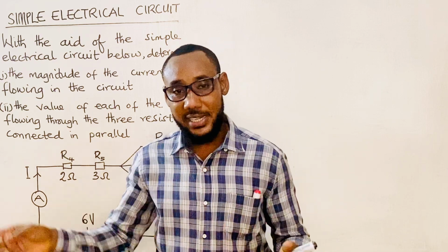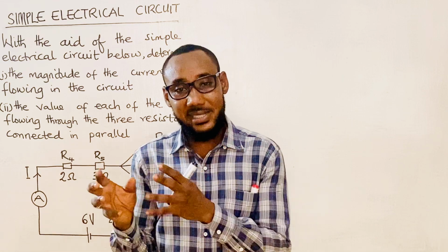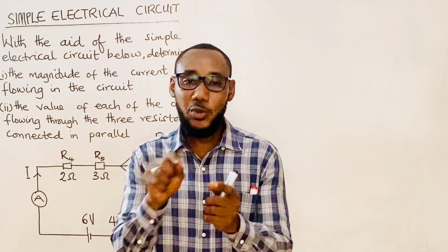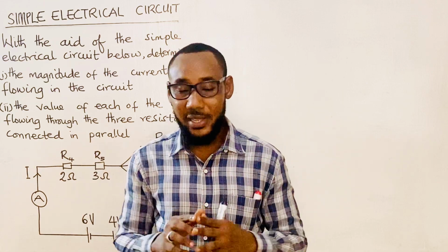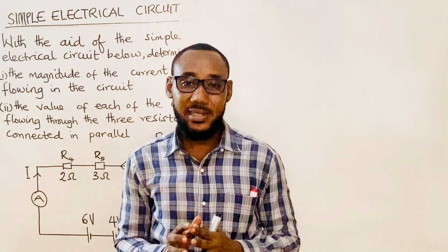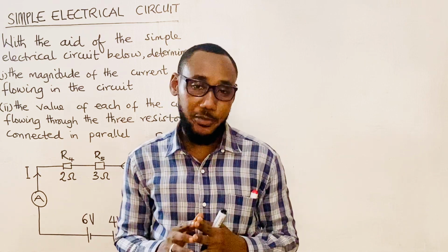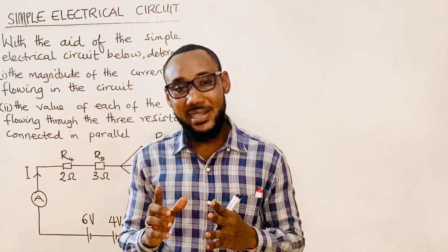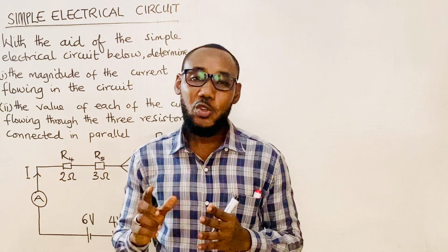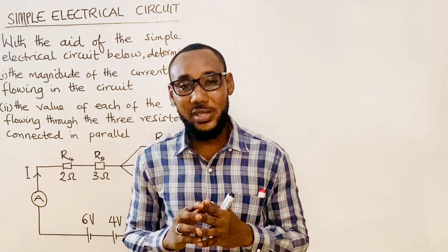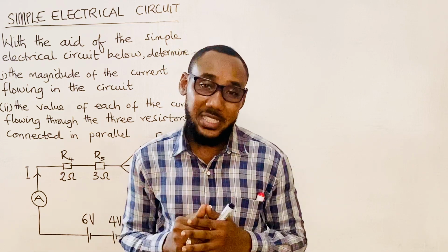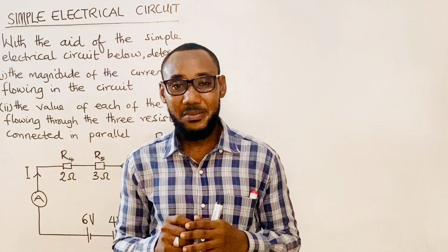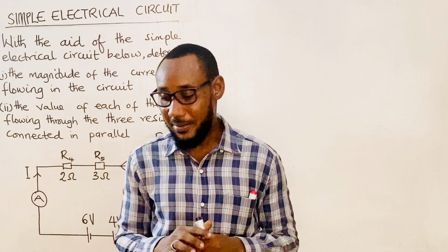The current flows through the circuit. Now these resistors usually have a potential difference across their ends which pushes the current through them. And then the whole circuit as a unit has what we call the electromotive force. Now the electromotive force is the work done in making a unit charge to go around the whole circuit and come back to its starting position. But the potential difference is the work done in moving a single charge across the ends of a resistor.